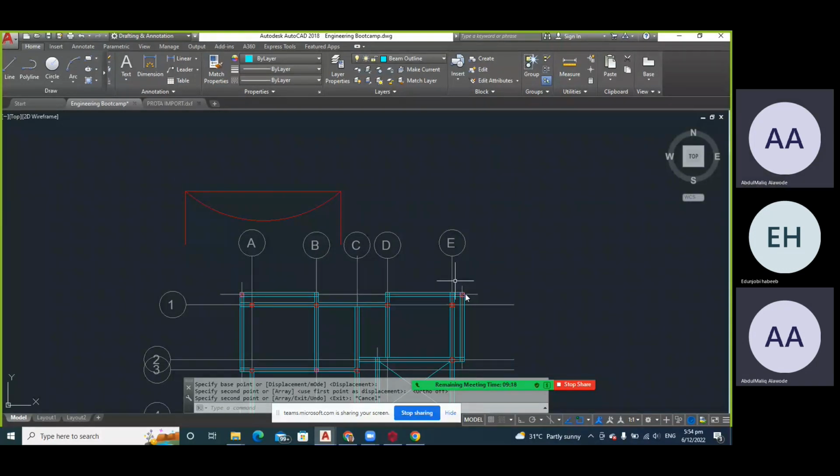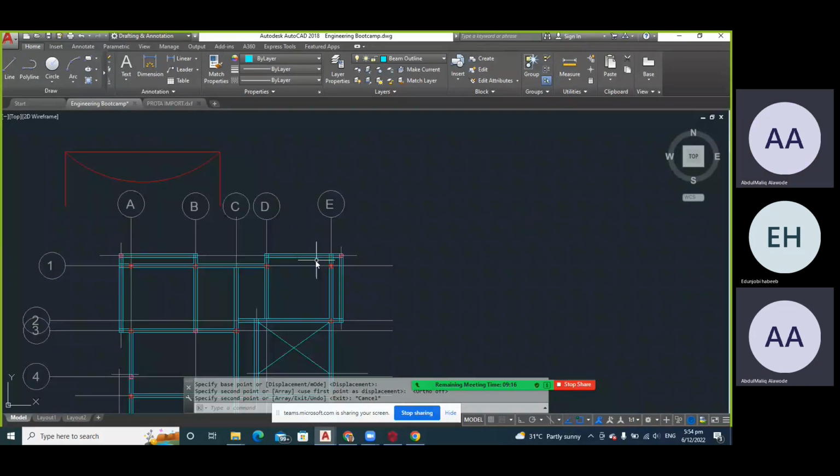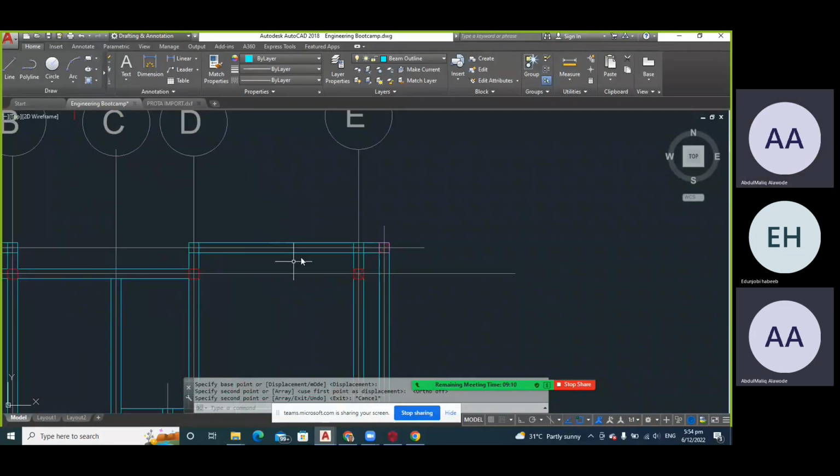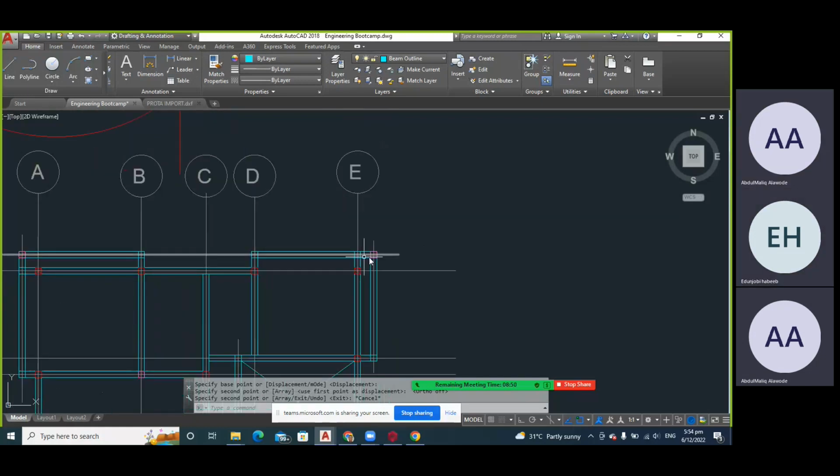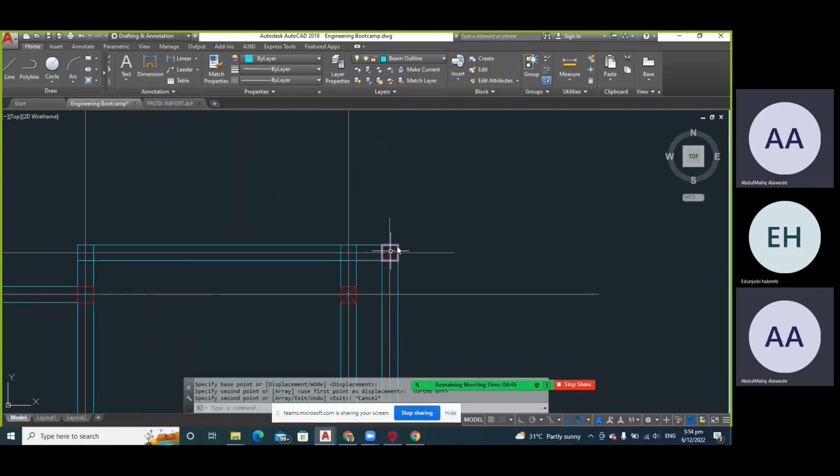Now I'm referring to this beam here. If I take the two ends to be hinged, which means the moment on grid line D and the moment on grid line E is going to be 0, which is wrong analytically. That's not how the beam will behave. There is a cantilever at the end, which is going to create a top moment.